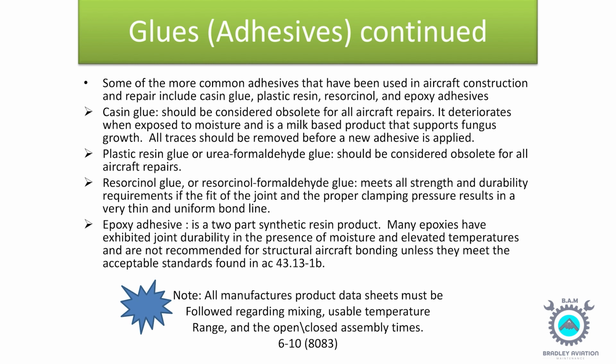Epoxy adhesive is a two-part synthetic resin product. Many epoxies have exhibited poor joint durability in the presence of moisture and elevated temperatures and are not recommended for structural aircraft bonding unless they meet the acceptable standards found in AC 43.13-1B. Note: all manufacturers' product data sheets must be followed regarding mixing, usable temperature range, and the open and closed assembly times.